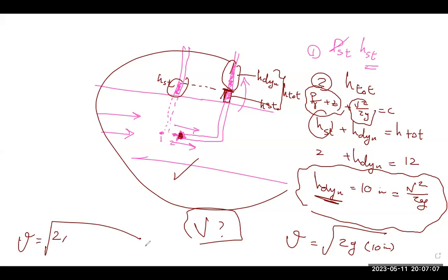Okay, so take care of this, please, and try to check it and solve it again to be sure you understand and everything is clear. Any question here? So how do you take this as stagnant? Is this end open or closed? No, it is not closed. The second pipe, with its L shape, makes stagnation for the flow. So the flow going into the L shape instantly stagnates. At this moment, velocity is equal to 0, so the energy is converted directly to head.